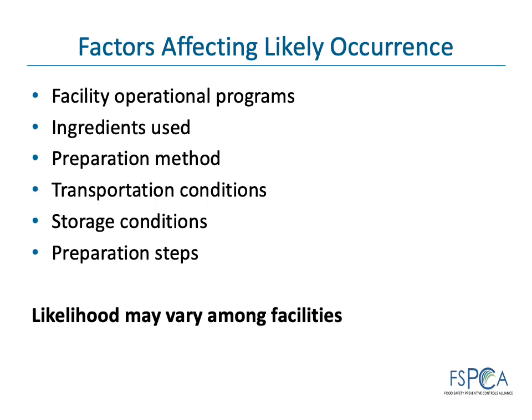The effectiveness of a preventive maintenance program can also be relevant in determining the likelihood that a metal hazard may be present. For example, Facility A may have a comprehensive preventive maintenance program that routinely inspects and tightens equipment nuts and bolts to prevent them from falling into product. They may couple this program with a review process for equipment designed to avoid installation of equipment with abrasive metal-on-metal contact. They may be able to determine that their prerequisite preventive maintenance program effectively manages the hazard of metal in the product because of their history of not finding missing bolts and lack of observing worn metal in equipment.